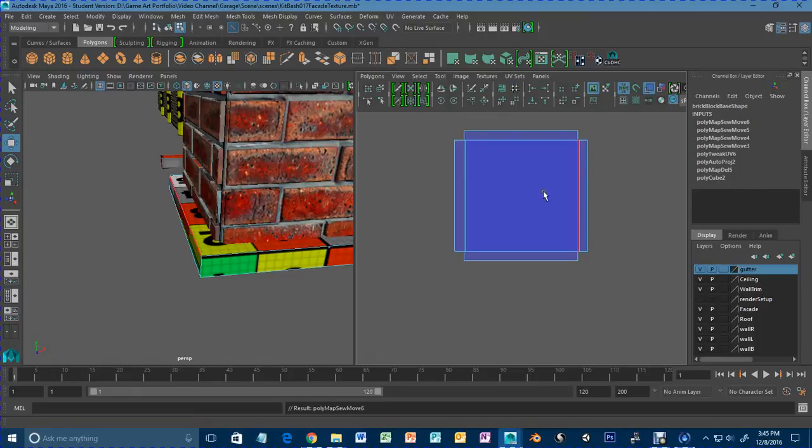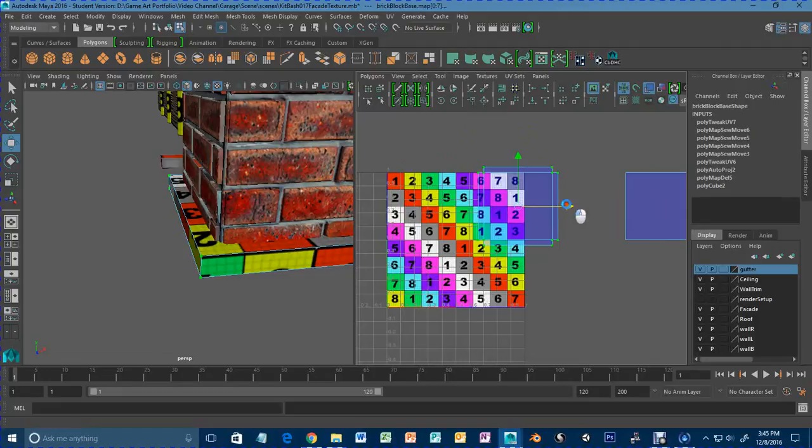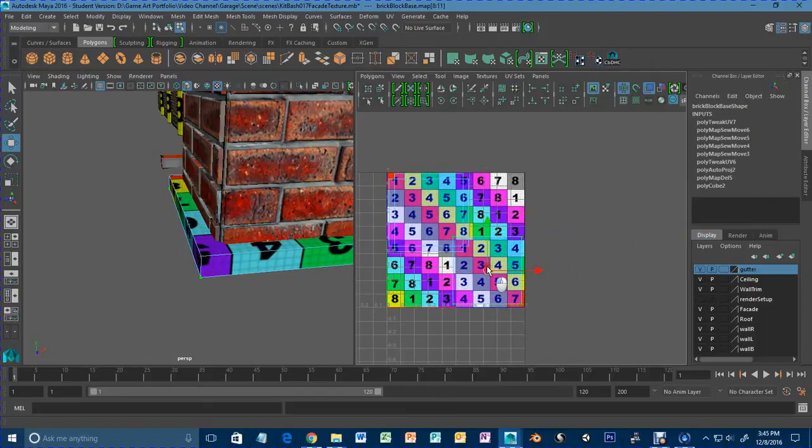It looks like they ended up overlapping. Doesn't matter. UV to shell. Bring it over. Bring that guy over. And since that's our bottom, I'll scale it down, because you're not even going to see the UVs anyway.